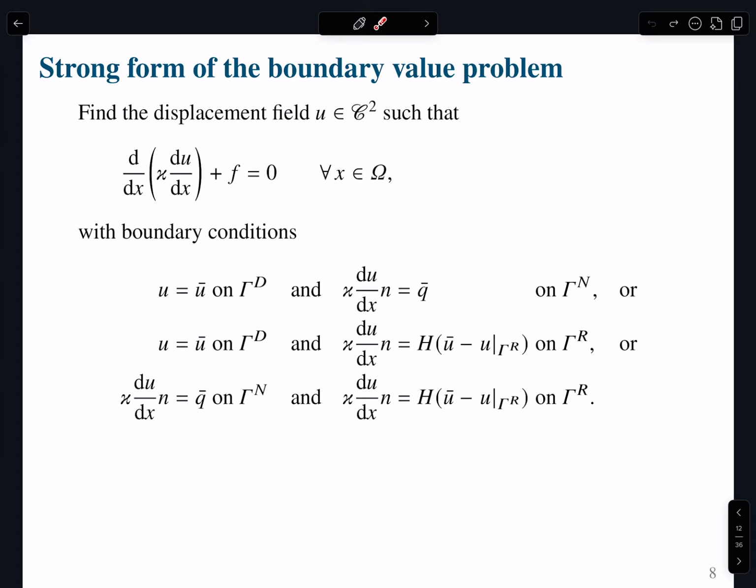And can we solve a pure Neumann problem? No. Yes, we can. We can solve a pure Neumann problem, okay? It's just singular. So how many solutions do you have in a singular system? Yeah, infinite. Can I pick any solution? Yes. And so again, you're going to solve the problem up to a constant. I'm just not going to know a specific temperature, but if I'm interested in the gradient, I can still solve the problem. You have a question?